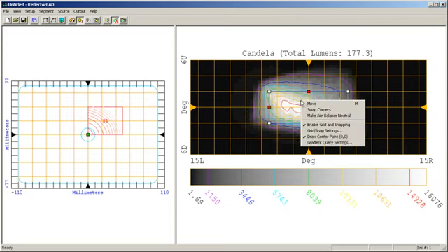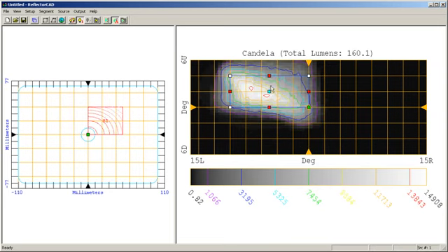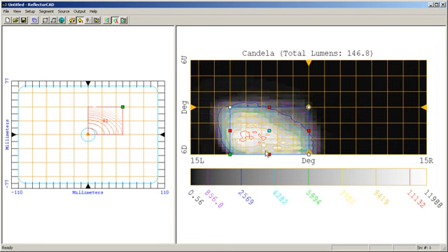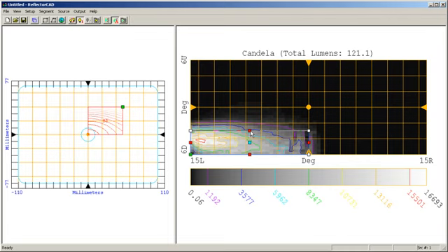In fact, what I will do is operate on the luminous intensity pattern, changing that pattern to the desired shape that I want from that particular segment by dropping and dragging the various areas around the luminous intensity pattern, and ReflectorCAD will automatically update the shape of the segment in order to produce that particular luminous intensity pattern.